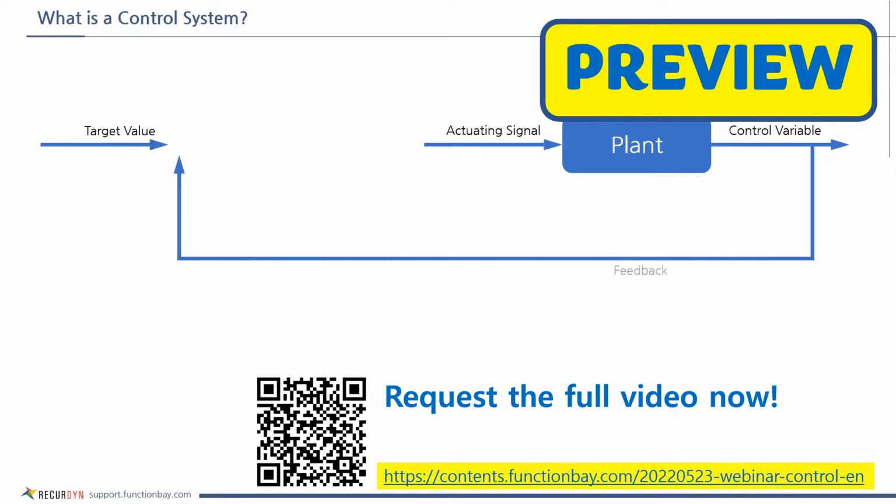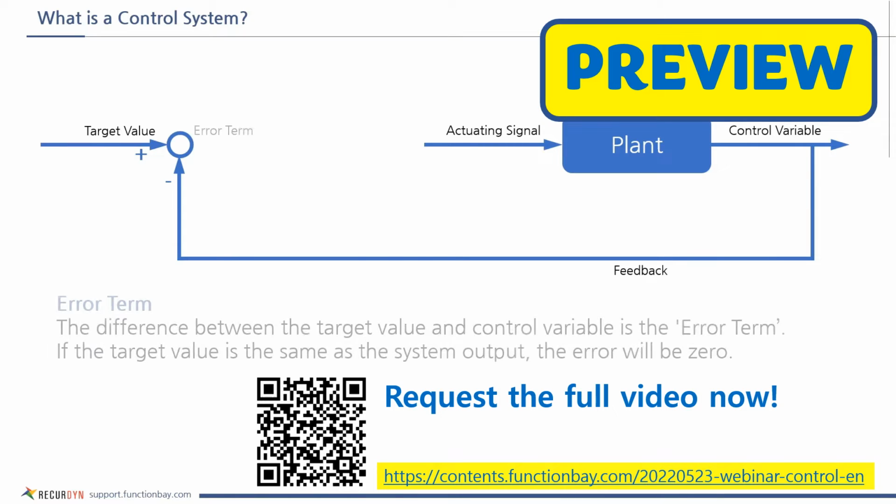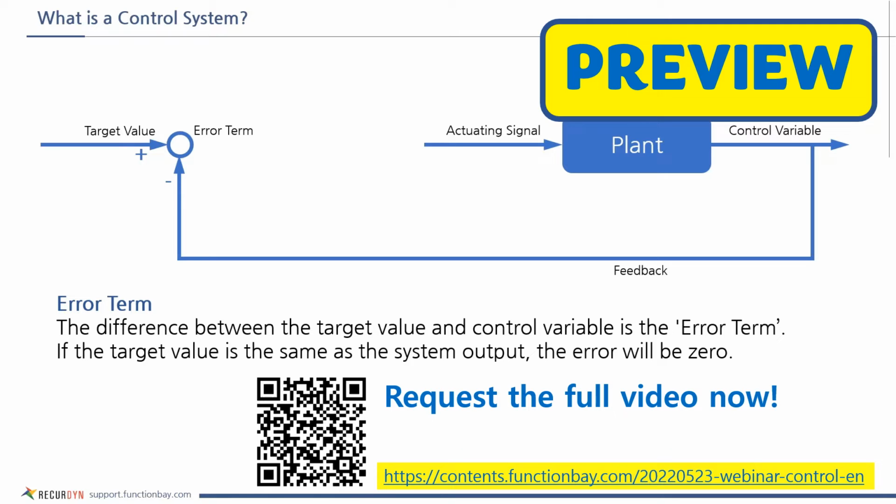In feedback control, the system output, which is plant output, is fed back. Here, the system's output means the control variable. And the difference from the current system is confirmed by comparing this feedback with the target value. For example, when a person travels to the destination, which is 50 meters away, the person is a plant. The distance traveled by the person is the control variable, and 50 meters, which is the distance to the destination, is the target value. The difference between the target value and control variable is the error term.